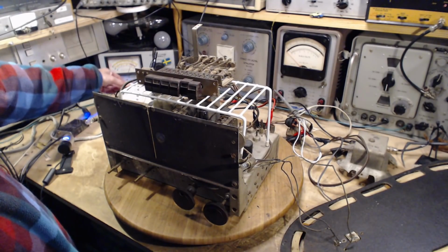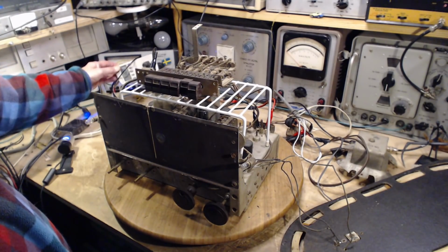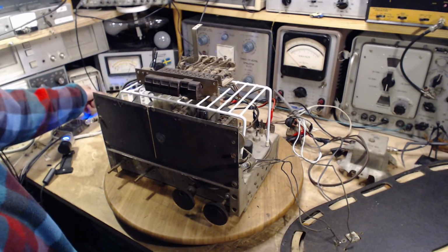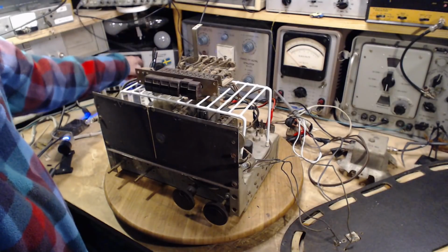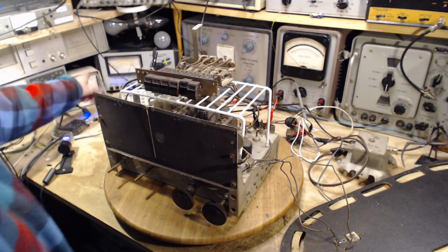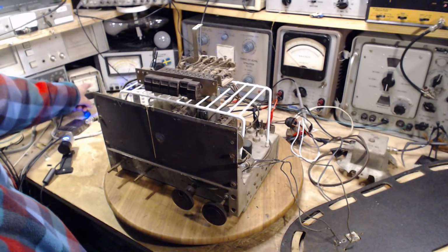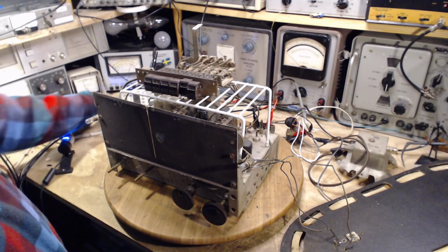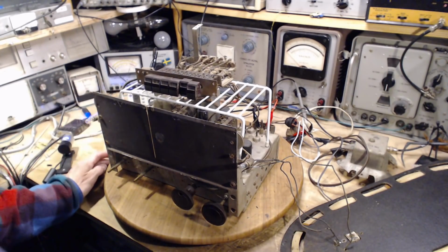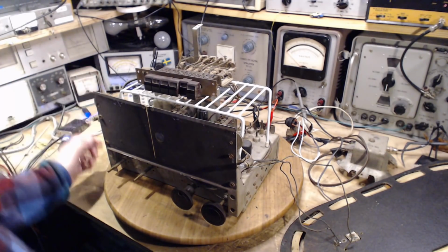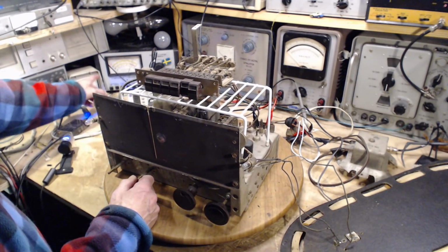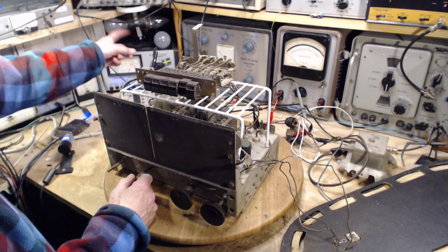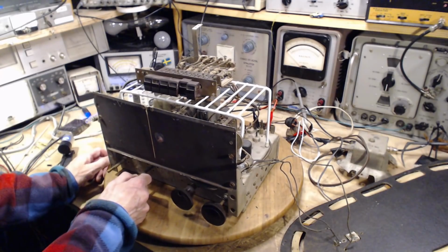And so is this guy here, but look, it's a little hard to see from a distance. This thing you can see quite easily. So that's the full voltage being sent, 115 on this meter. Actual voltage 117. Okay, pretty good. This meter's fairly accurate. When I hit the switch here, you'll see this meter just drop right off. You'll see the lights come on a little bit and stuff like that. There we go.